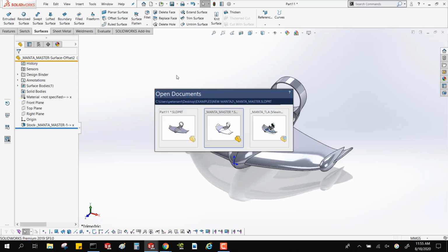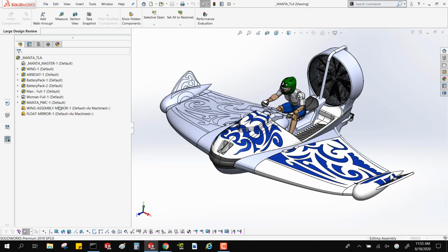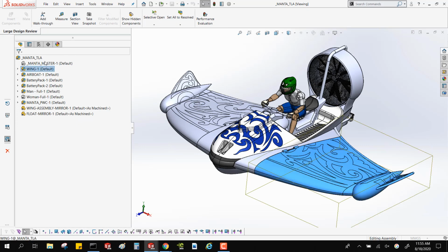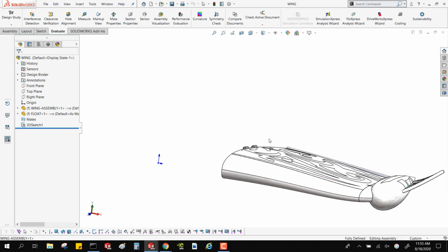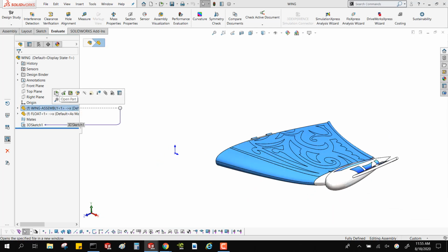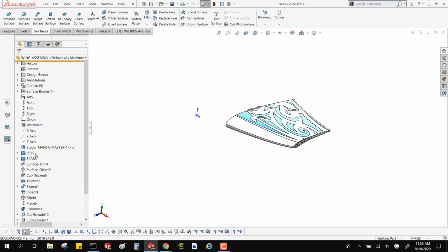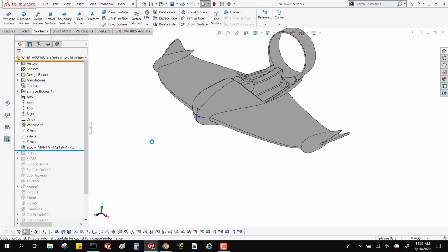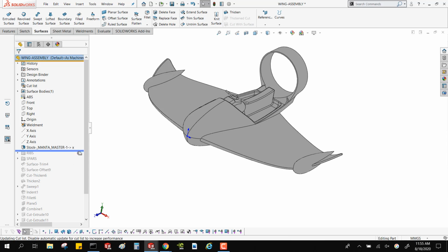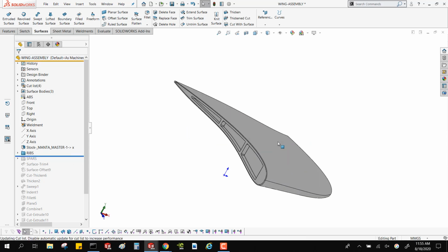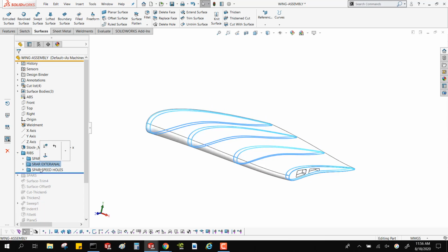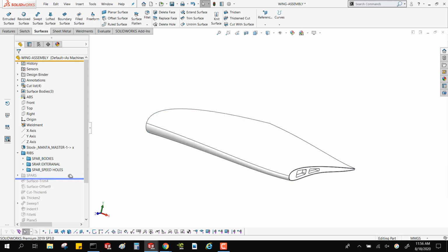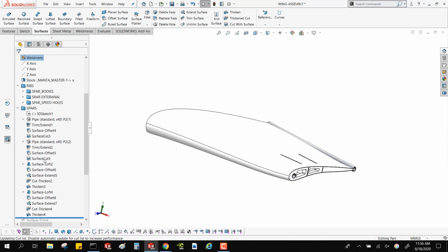But when you've got an overmodel like that, where this is the whole thing, I can bring in this assembly and show you how I was able to create this wing very quickly using the surface geometry that I just showed you. So if I roll back, there's our friend, the whole shape. And then I'm just working on the wing. So I sliced everything that I didn't need away and started using the geometry of the surfaces to help me build these spars and ribs, fully featured out.